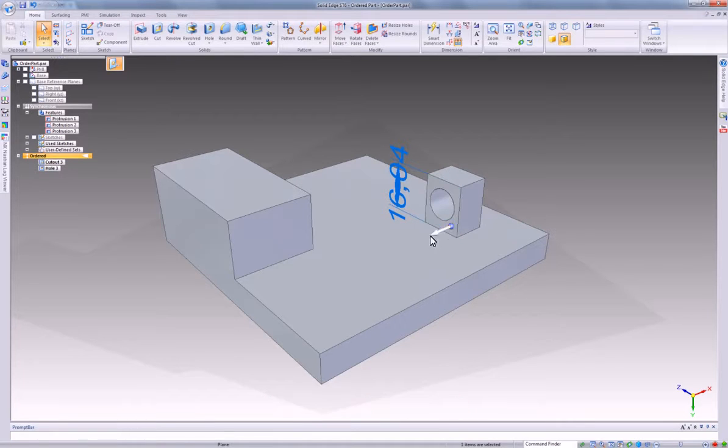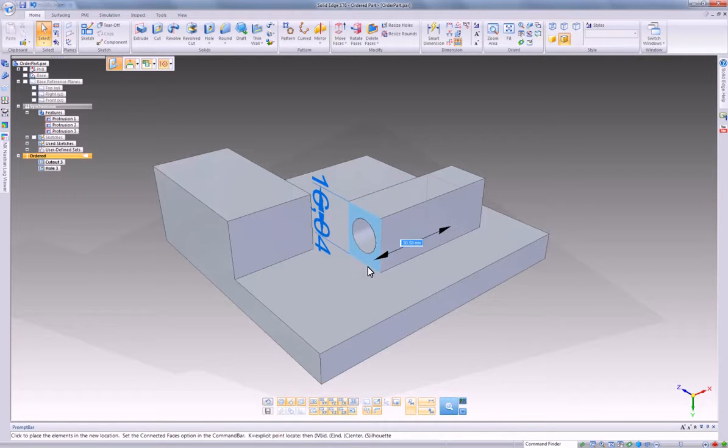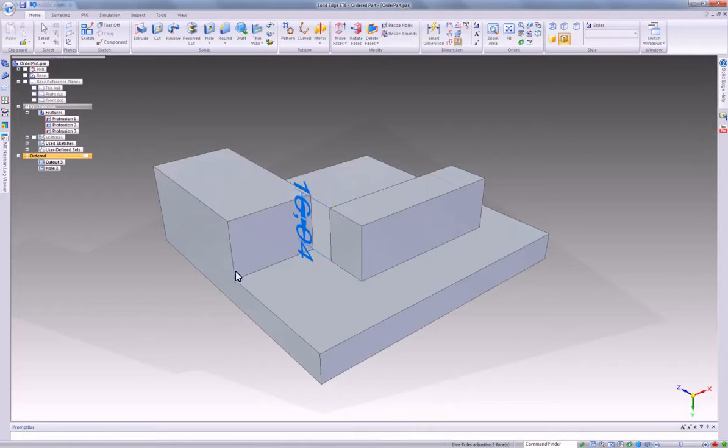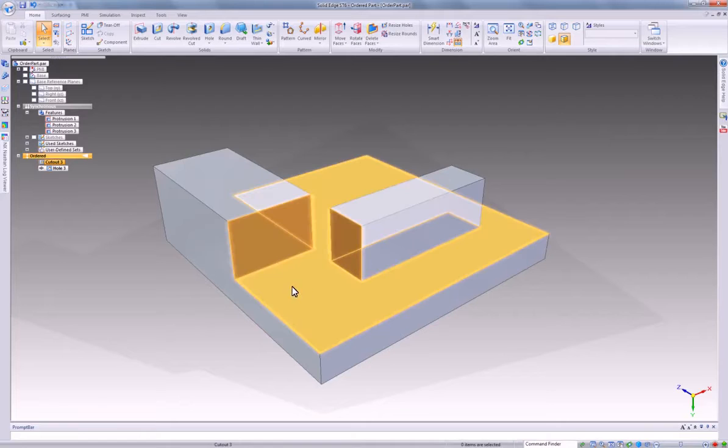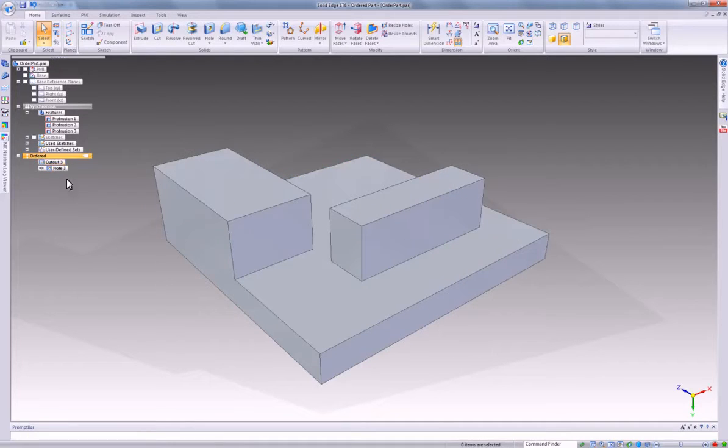So if we pull this feature, you'll notice as we pull this out, it's working so far until it hits this area where the feature cuts out. This is because the order dependency is still in place and it doesn't basically give a user a predictable result. The user would expect that when they move this out, it would show up in the region where they're moving it, but since these features still exist here as features that are added later in the history, it still cuts off the object at its plane.